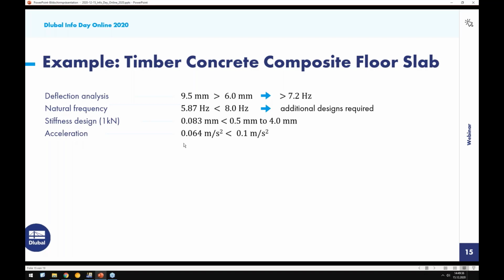So there are tests showing that this velocity check, which is done in the Eurocode, is actually not really design-governing anymore, because a typical timber floor, for acoustic reasons, is already really heavy and the weight is really high. Therefore, the velocity check is mostly never controlling and not important. But the acceleration needs to be checked.